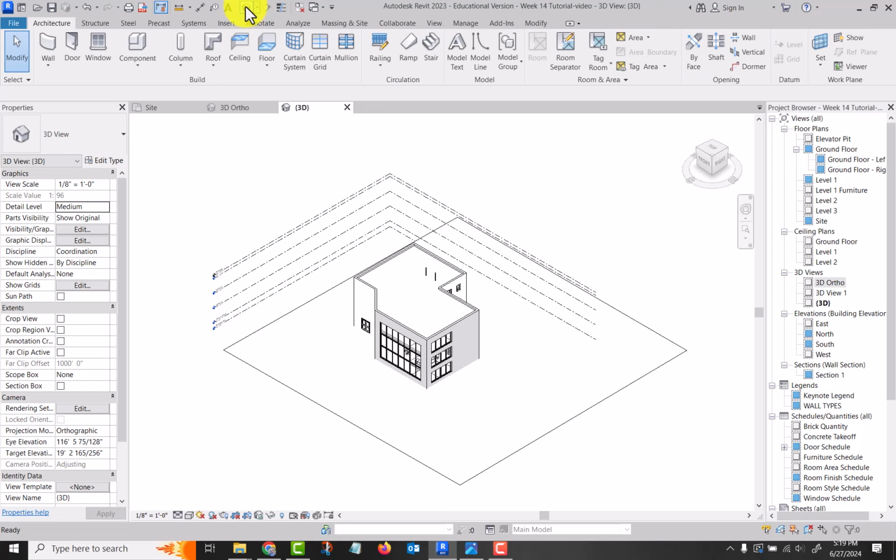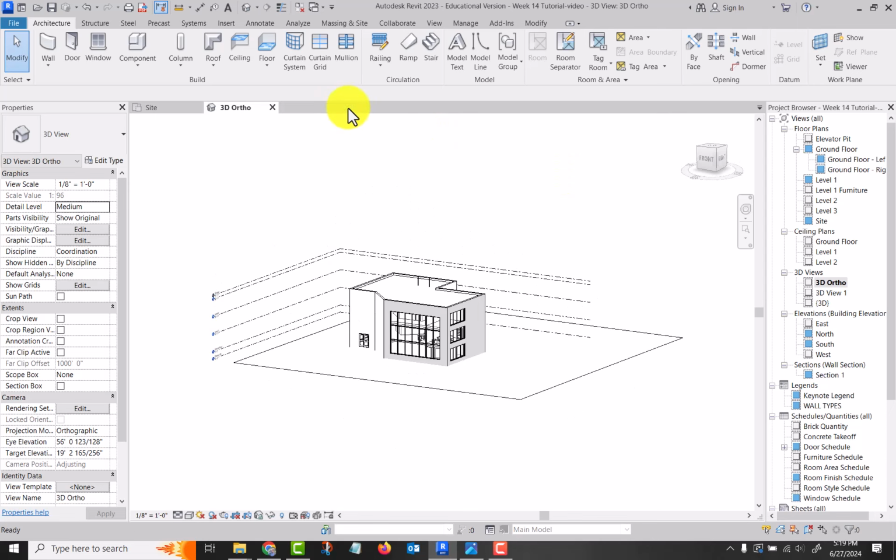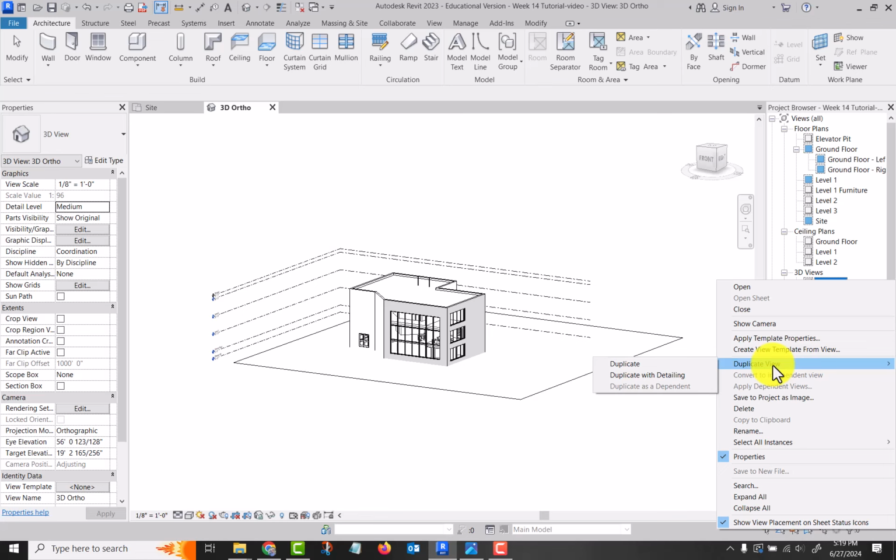And one of the things about all the 3D views, if you use the view cube or the compass up here, you're changing the location of the camera. Okay, so there's ways to manipulate your views without doing that, but when you work on the default, that's the way it happens.